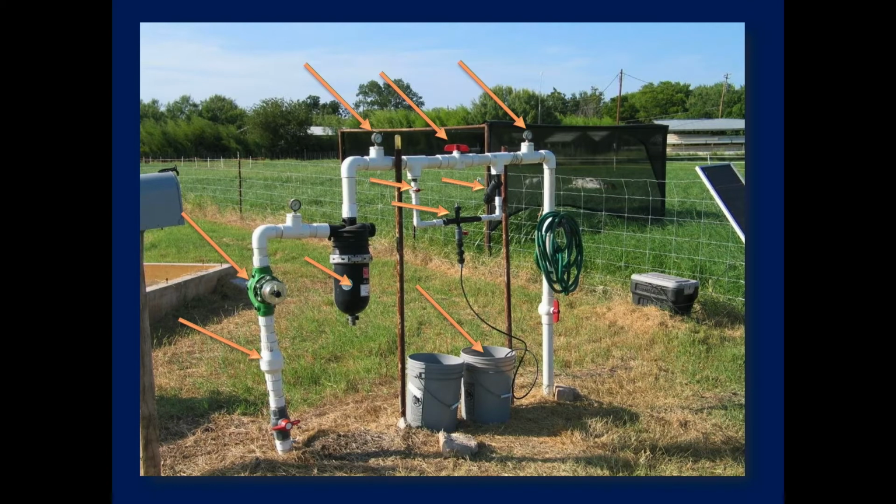So the water goes through, it cleans it up, you inject it, you still have water going through here, you've got fertilizer coming up through here, it gets mixed in here. You've got another small Y filter, that's WYE. This is a screen filter. This gets any particles of undissolved fertilizer out of there, because small particles of sand are actually big enough to clog emitters. So you want to do anything you could possibly do to make sure you block any of that stuff at this point. And of course you've got the outflow here.